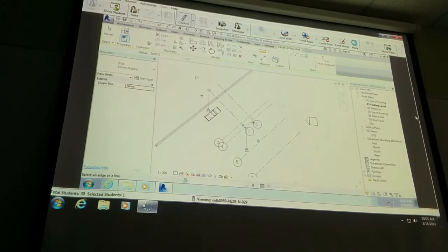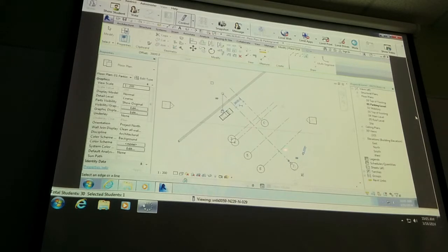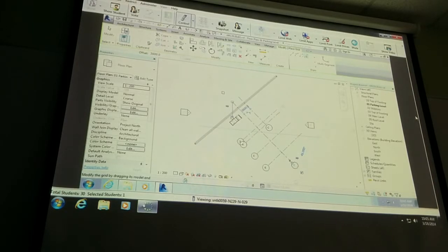Now I'd like to take that grid line, as you can see, and stretch it down so that its tag is down about here. In order to stretch it without stretching grid line C, you need to unlock the padlocks. In other words, you select it, unlock the padlock at the end. That allows you to take the grip and stretch the grid line. You want to maintain the same angle as you do that. That's going to be grid line B.